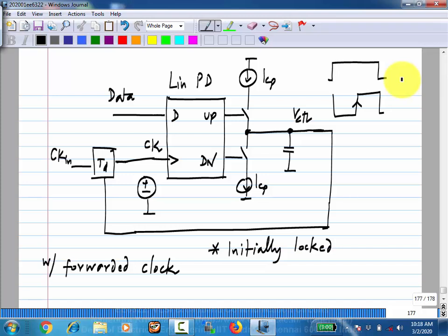So now I will make a clock source which generates this exact waveform with its rising edge in the middle of data. And I instantly swap this feedback derived connection with this. So do you agree that this clock will still be in the middle of the data?